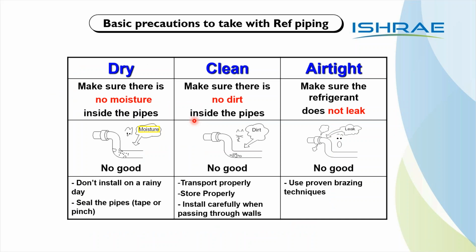Then the most important part is we never clean the pipes or the fittings before we use. Please note, R410A refrigerant is very sensitive to moisture and non-condensable gas.